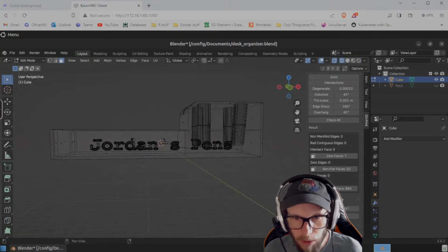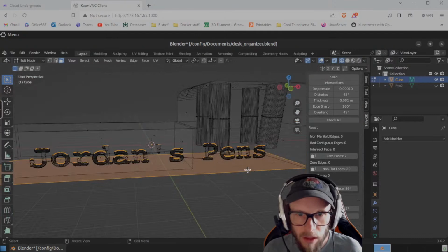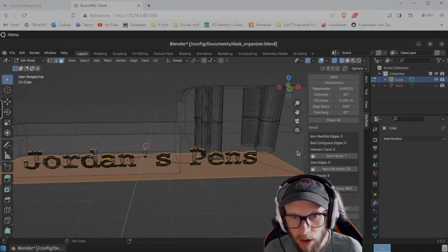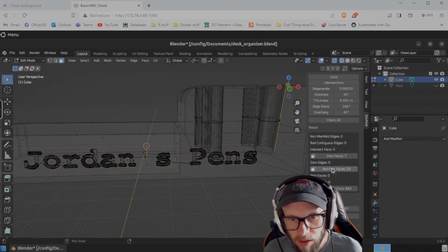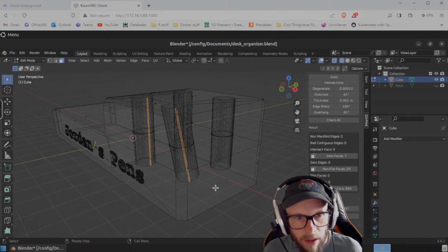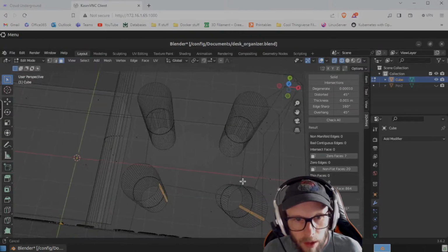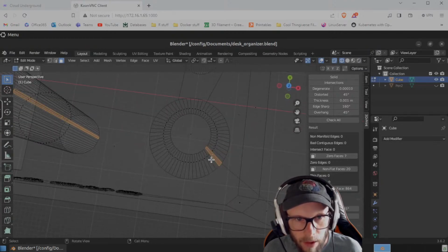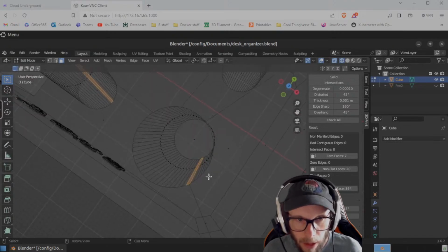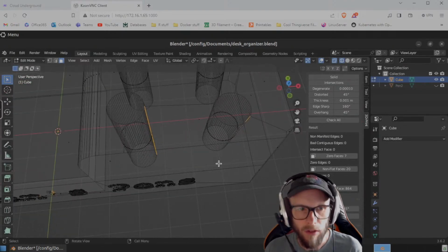And of course, then it's complaining about all these overhang faces. That doesn't matter. Really, what I'm tending to look for is intersect faces, any of these really. Thin faces, non-flat faces, zero faces. So non-flat faces are faces that they have some, like, so these are rectangles, right? You can actually have them not be all in a plane, and that causes them to be considered non-flat.